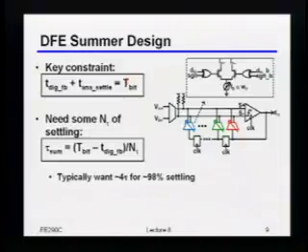Okay, so the other piece of bad news here is, remember I said I have these analog voltages on the line here? Generally speaking, I want to settle those things out within this analog settling time, meaning I want them to be fairly precisely the actual value that they were supposed to be, right? So the time constant you have to achieve on this summing node isn't just set by t-bit minus this digital feedback delay, but actually I need some number of those time constants within that t-bit minus the digital feedback delay, right?